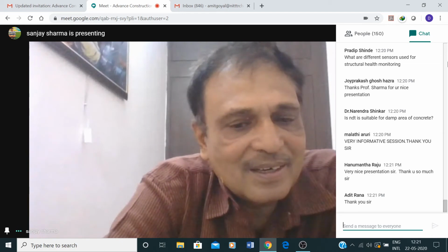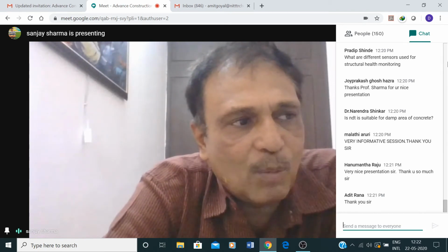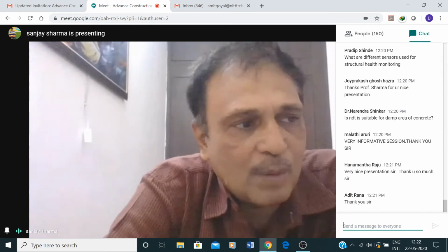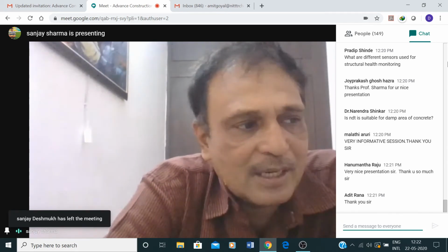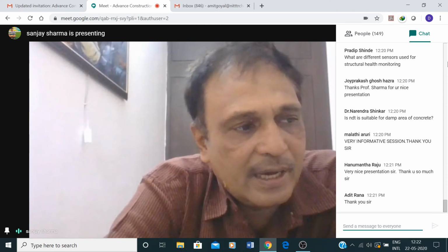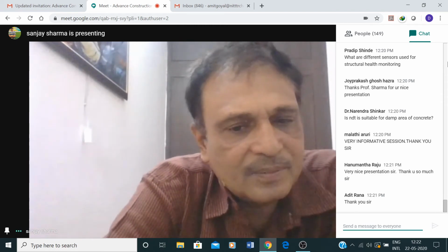Is there any code? Indian codes only for ultrasonic pulse velocity and rebound hammer are there, 13311 part 1 and part 2. All the others are basically either British Standard or ASTM standards. Indian standards are not there.